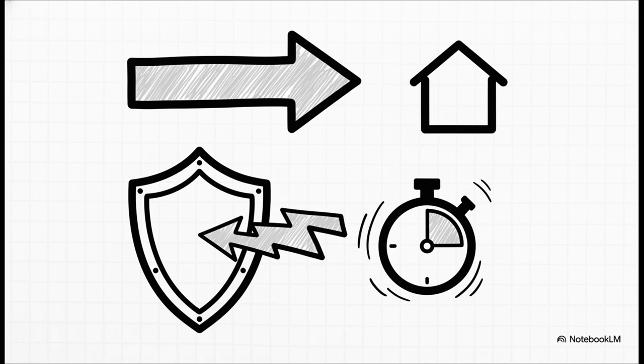To pull this off, engineers use a very specific setting philosophy. The core assumption here is that normal, everyday load current always flows in the non-operate direction, meaning toward the load. So absolutely any current flowing in the reverse, operate direction is a 100% guaranteed sign of a fault. Because of this certainty, these directional relays can be set to be hypersensitive, typically triggering at just 50% of the normal load current. And they can be set for lightning-fast operating times, like a time multiplier setting of 0.1. They don't need to sit around and verify. If the current goes the wrong way, boom, they act instantly.